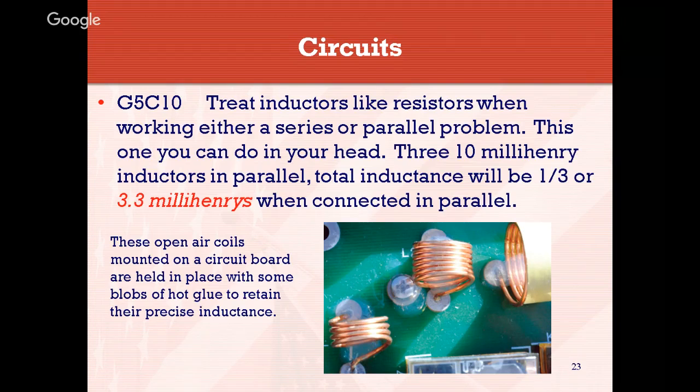These are open air coils, and they're mounted on a circuit board held in place by some blobs of hot glue to retain their precise inductance. If you were to go in and spread those apart, it will change the inductance of that coil. So typically, what the manufacturer does is they put them in place that way for the precise inductance that is needed for that particular circuit. So don't go spreading those things apart if you're digging around inside your radio. You could change a few things, and that's not always a good thing.